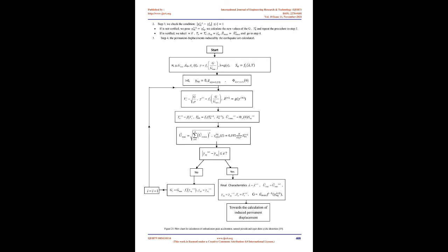4.2.7 Calculation of induced permanent displacements. Knowing the value of the acceleration at the crest of the embankment, using the chart in figure 7, the value of the maximum acceleration coefficient of the unstable part of the embankment is determined. The ratio is calculated. If this ratio is strictly less than 1, the induced permanent displacements are given by the charts in figure 8. If this ratio is greater than 1, the embankment is stable and the calculation of the induced permanent displacements is not applicable.